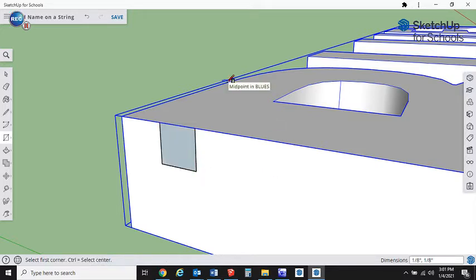So click, release, drag, place it, and then we're going to make this so that it is 0.1, comma, 0.1, enter. So basically a 1/10 of an inch. That's generally a good size, good enough for this to print and be able to get a string through no problem afterwards.